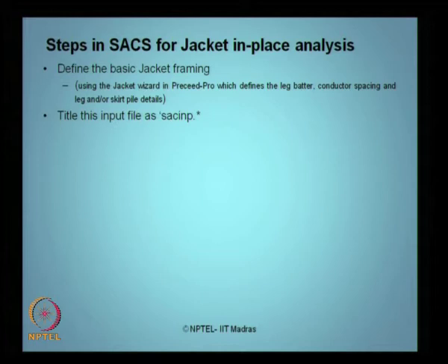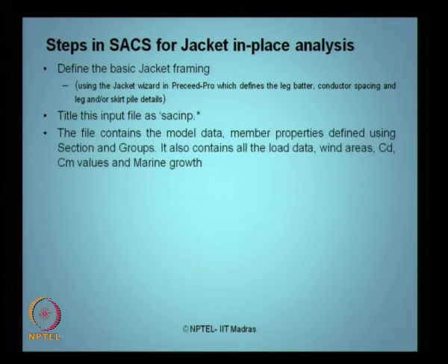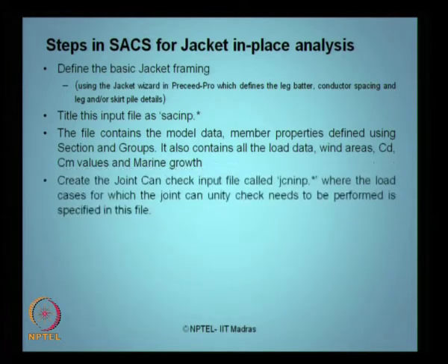Then title this input file as SAC input dot star, maybe the extension is generated automatically. The file contains basically the model data for your problem, the member characteristics and properties defined using the sections and groups. You can even group them, and you can give separate sections for each leg as well. It also contains all the load data, the wind areas, the CDCM values and the marine load details all along the length of the member.